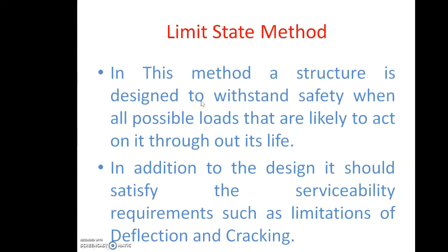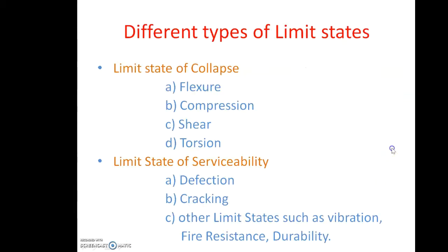Limit State Method. In this method of design, a structure is designed to withstand safely all the possible loads, that is dead loads, live loads, wind loads, earthquake loads and snow loads that are likely to act on it throughout its lifetime. In addition to the design, in the limit state method, we will check the structure for serviceability requirements such as limitations for deflection and cracking.